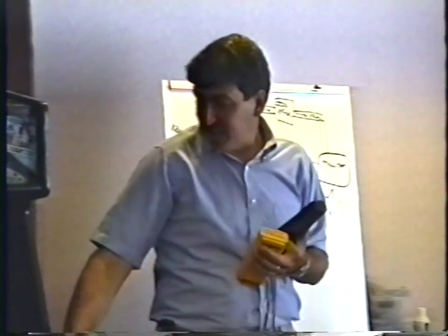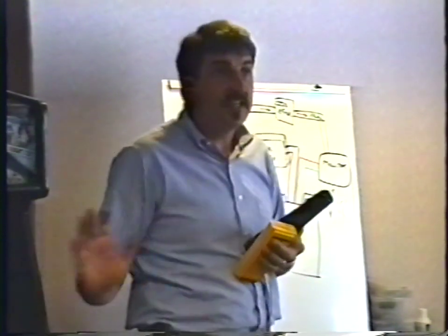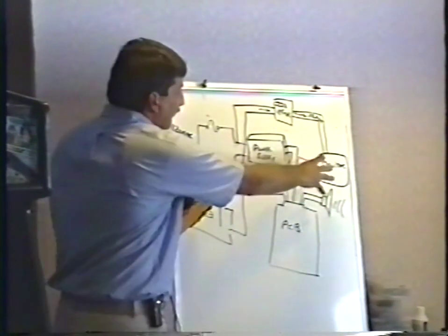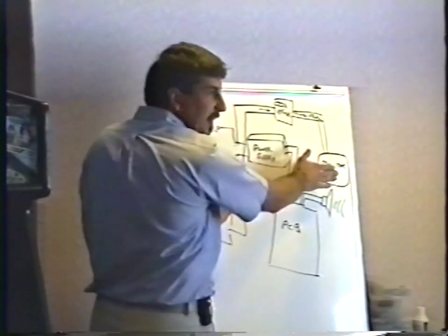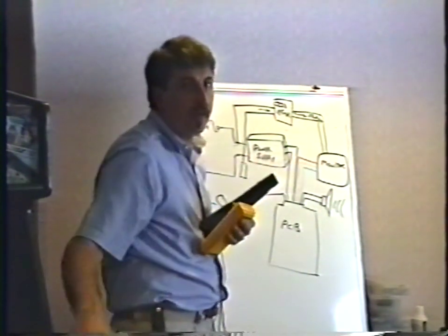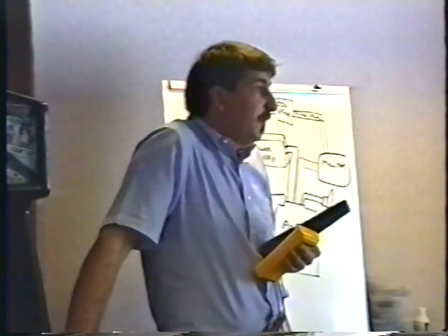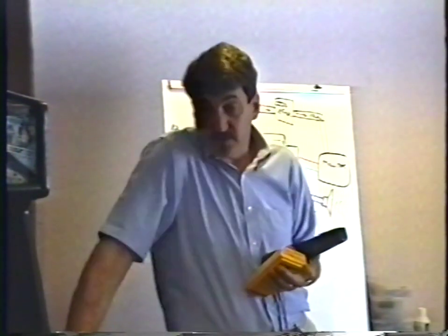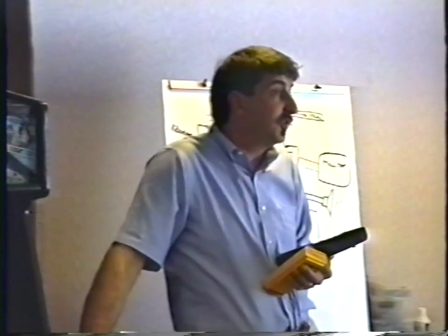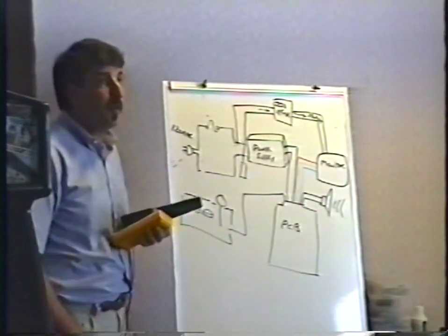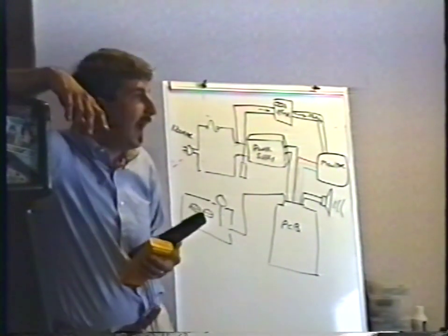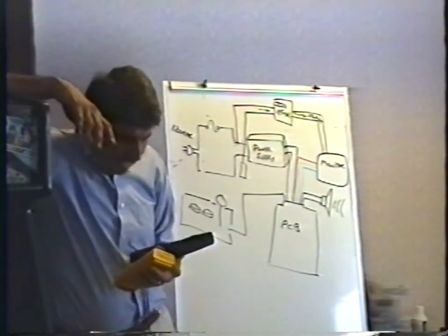The reason the monitor isn't showing anything is that the power supply is not powering the computer, so it's not putting out those red, green, and blue signals that go to the monitor, and that's why you're not seeing anything on the screen. Wouldn't it be really stupid to rip the monitor out and start working on that when there's nothing wrong with it? So by coining, I know it seems so simple. You coin up the game, you press the start button. You'd be amazed how many people don't think to do that. It's such a simple thing.